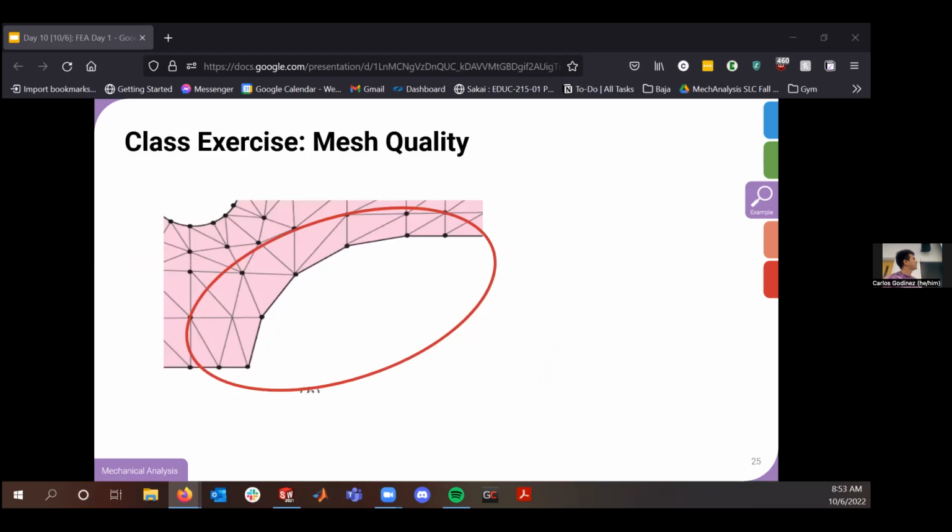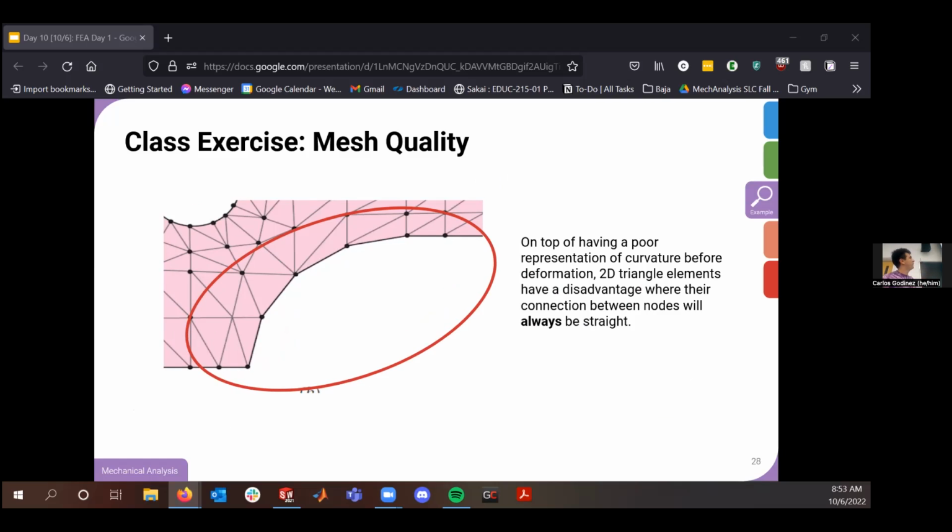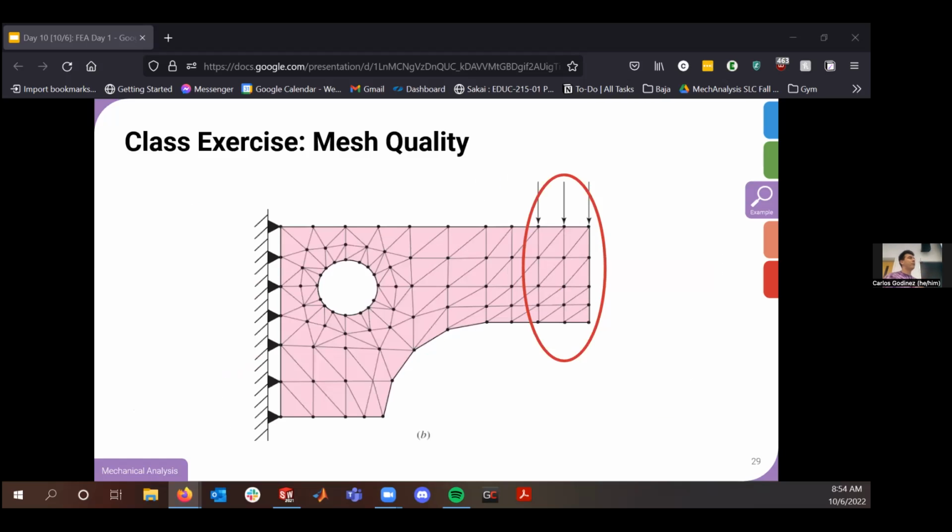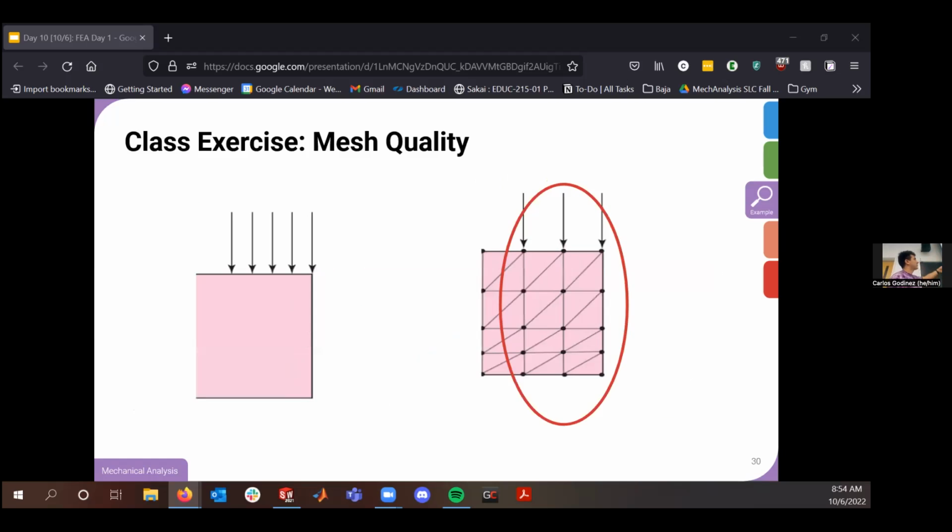Yeah, perfect. If I pull this out over here, remember, as we mentioned, distributed loads and supports can only be provided at the nodes. So for that distributed load I had beforehand, I can really only distribute it across these three nodes. And notice for my fixed support here, I can only fix it at the nodes that are connecting at the wall. That brings home this point: we had a distributed load that now we're only applying at three points.